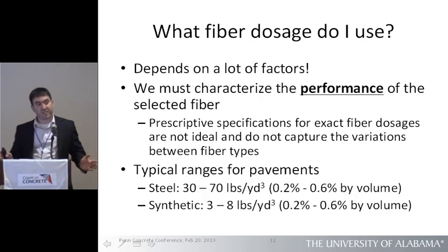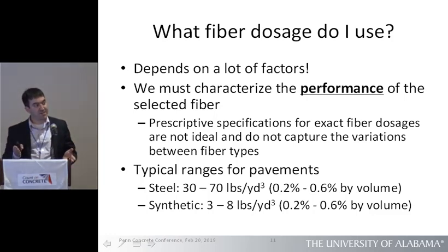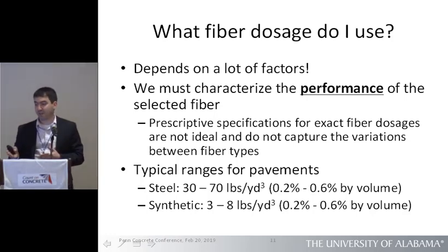But regardless of that, if I'm going to stick fibers into a concrete pavement overlay, the question I always get, and that the co-authors of this document always get, is, well, give me the dosage. I need to know how much fiber to stick into my mix. Well, you can't do that unless you know a few things about the concrete, where it's going to be placed, and the expected traffic loading and all that.